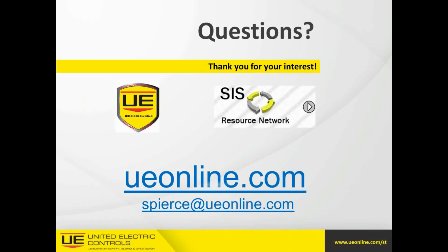The products that we make specifically are these that you see in front of you. They are safety transmitters for pressure, temperature, and differential. They are all SIL 2 certified and SIL 3 capable by Exida, and they all carry a safe failure fraction of 98.5%. There is no other instrument on the market today for pressure, temperature, or differential that carries that high a safe failure fraction. The reason is that this device did not start out as a process variable device. It started out from its creation as a safety transmitter. So from the ground up, we created it to be a safety transmitter, and by doing that, we were able to build in all of the checksums that we know the industry is looking for, to create the highest safe failure fraction known in the industry, 98.5%.